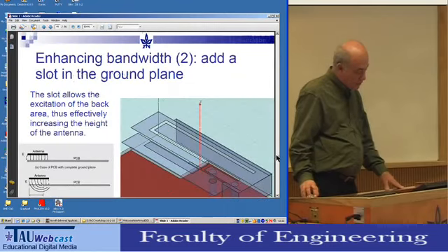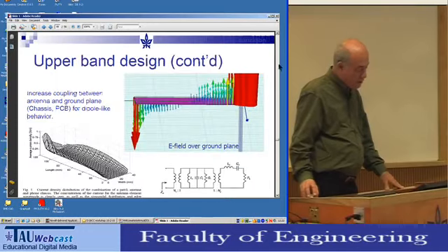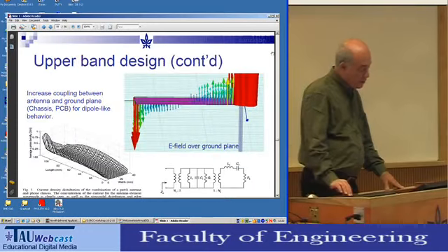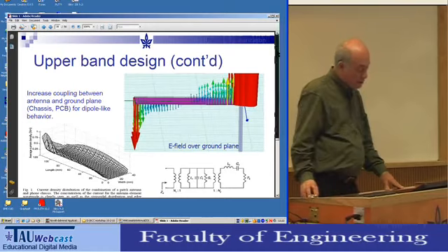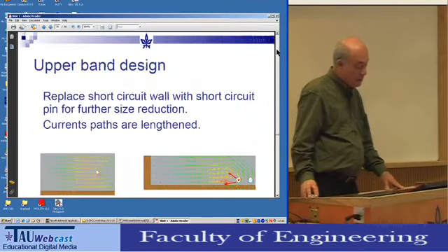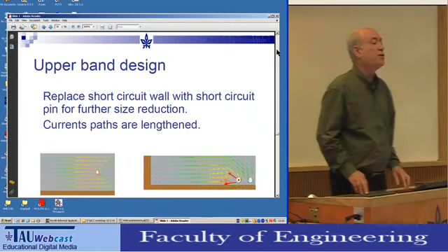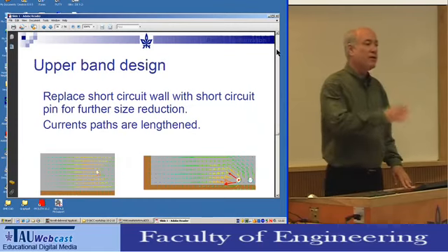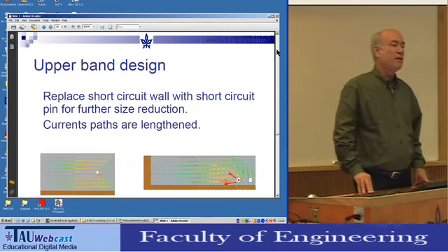If you want to bring the antennas any closer than lambda over, say, 3 or so, they will interact. So this will have an effect on the correlation between signals. We're looking at some correlation stuff also to figure out how that works. Lambda over 2 or something is the rule of thumb that applies.